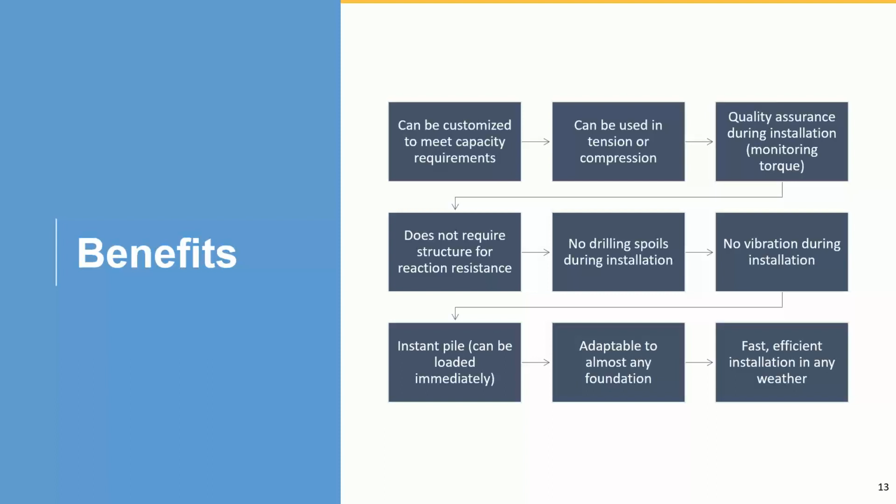So they are fast and easy to install. Like I said, I installed these helical piles. I told you the 2 7/8-inch outside diameter shaft is not that heavy. We don't need machinery to pick it up. You have somebody just pick it up, put it in there, and boom, install it.